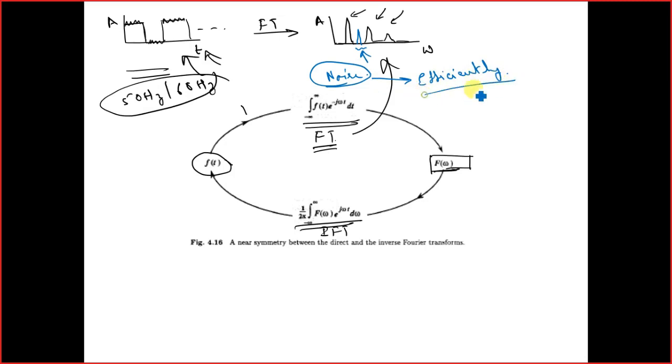Now you have designed the filter, which works in the frequency domain. Now again from here, after filtering, you want to go back to the original time domain signal. You apply the inverse Fourier transform and you get the denoised signal. So this is how the Fourier transform helps.